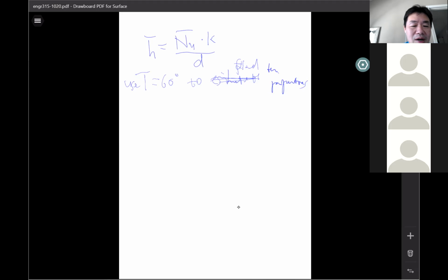Okay, so with this, I think you got the density, 985 kilogram per cubic meter, right? That's what we needed for calculating the mass flow rate. Cp, we know we need that for the main energy equation, 4.18 kilojoule per kilogram per C. Okay, viscosity.